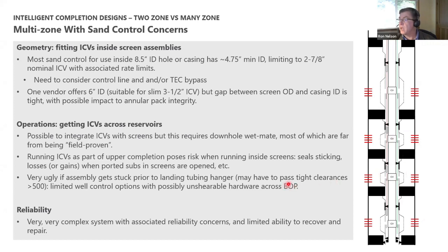And the other concern is around reliability. You have this very, very complex system with all these connections and splices. It has a higher risk of failure, and once this is installed and you start production, you start getting some fines from each of these zones settling on top of these seals. Assuming you can get this installed, I doubt very much that you'd ever be able to recover it for repair. So if you had a failure, you either learn to live with that failure, or you have to replace the well in its entirety or sidetrack the well, and that obviously comes with cost as well.